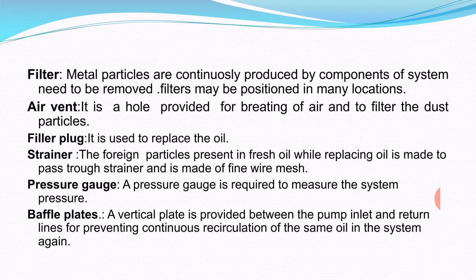Air vent is a hole provided for breathing of air and to filter the dust particles. Filler plug is used to replace the oil, meaning you can refill it. Strainer: the foreign particles present in fresh oil, while replacing oil, are made to pass through the strainer, which is made of fine wire mesh.